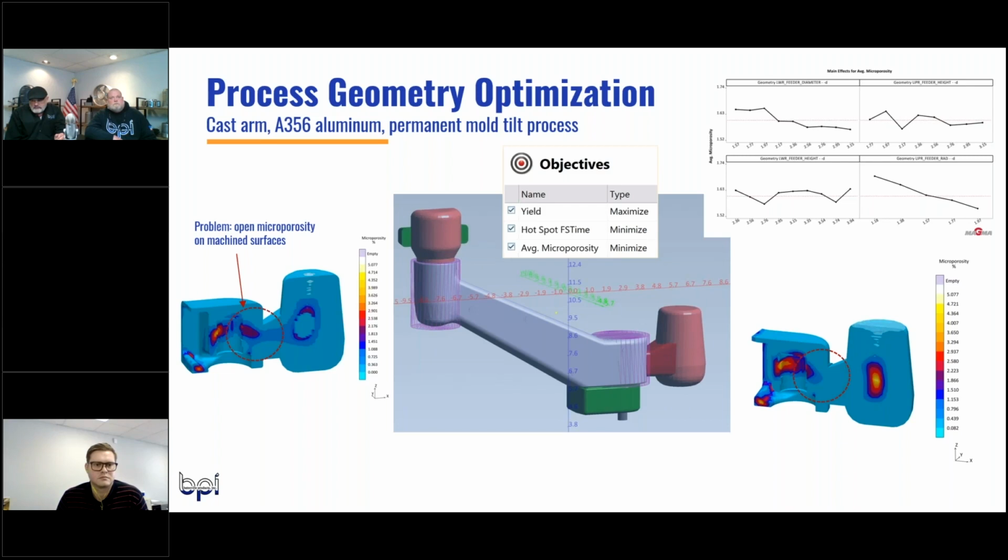So once again, we're not just considering one design or going in a serial way of physically or manually changing the size of the riser. We're plugging in a large number of reasonable casting riser designs and trying to figure out which combination of the two will give us the lowest micro shrink with the optimal casting yield. So that's really the power of using this tool on the front end, before the tools are cut and physical sampling in the foundry begins.